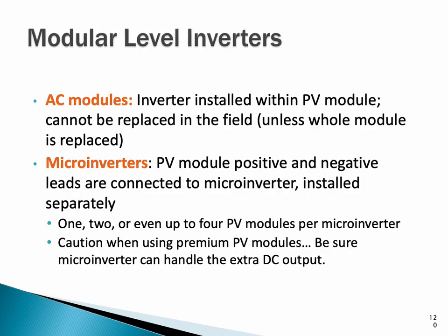The microinverters, again, those take the DC, put out usable AC, and these are becoming really popular. I think it's 90-some percent of all systems that are installed are either optimizer based or microinverters, and the big players in that are SolarEdge for optimizer based systems, and then Enphase for microinverter systems.